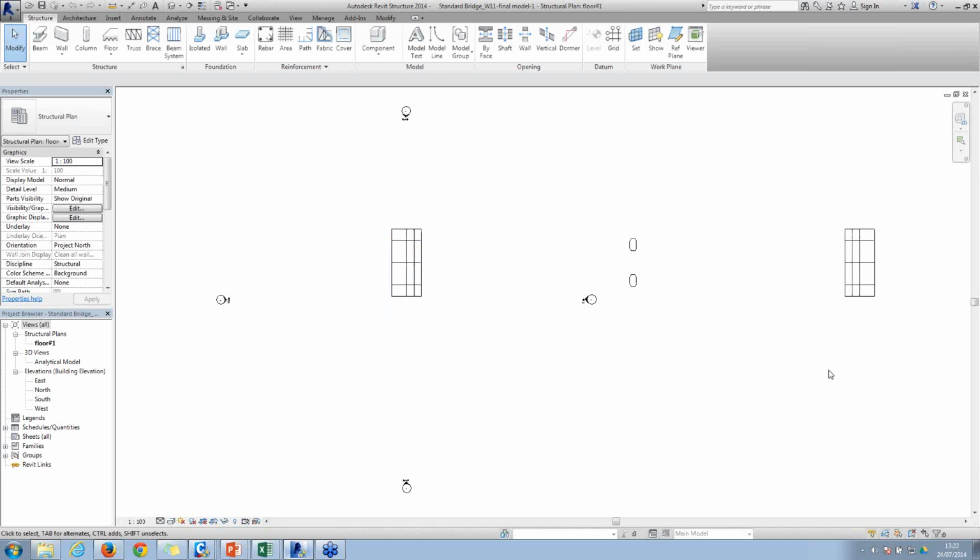So normally for glass, we'll go for orthotropic material, and we use plate elements for the decks, so not composite sections. We used a grillage model in today's example, but instead of a grillage model, we model the slab as plate elements for such type of user-defined sections.